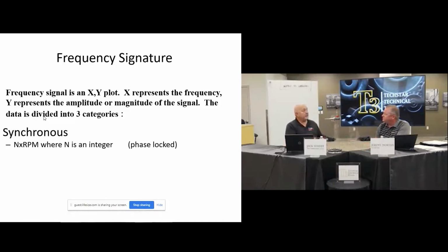Yes, if you had some type, that would help, but you definitely have to know what the RPM of the machine is. Some of the analyzers that are out there, when you collect the data, you can actually locate the 1x peak in the spectrum and label it as the RPM. Oh, so that's your reference point. Yeah, you can set your reference by doing that. So it's more of an inferred measurement, though. It's not really a measured variable at that point. Right. And a little variation there sometimes.